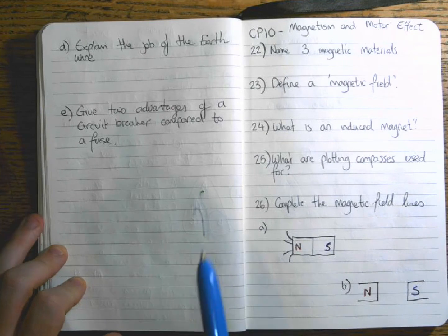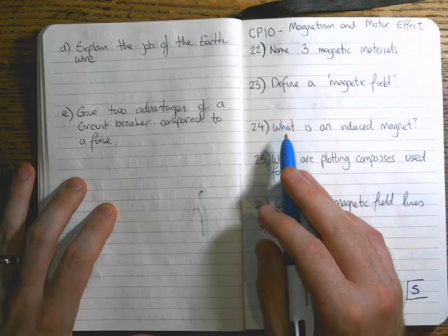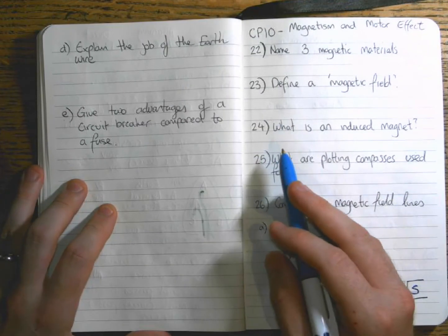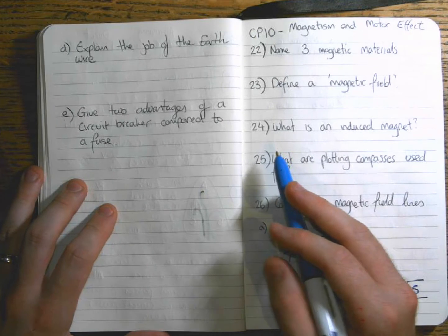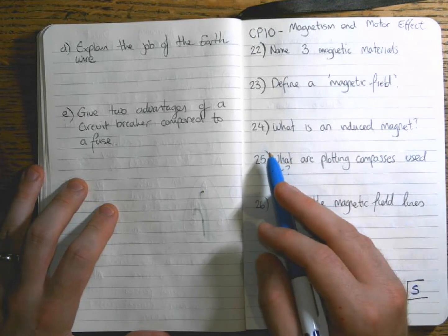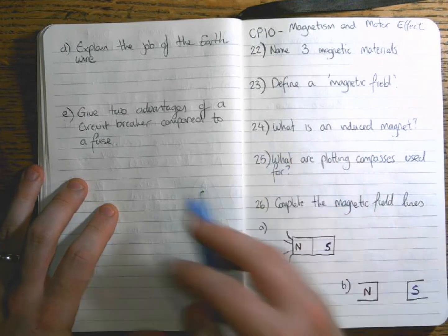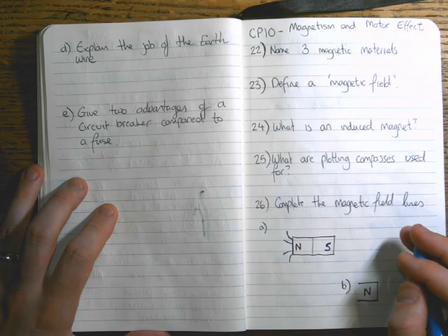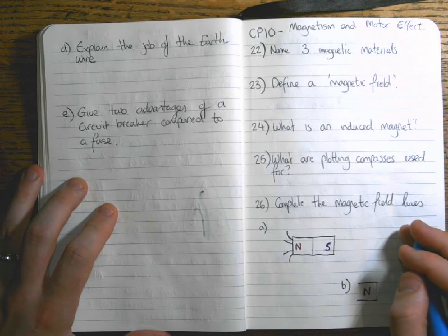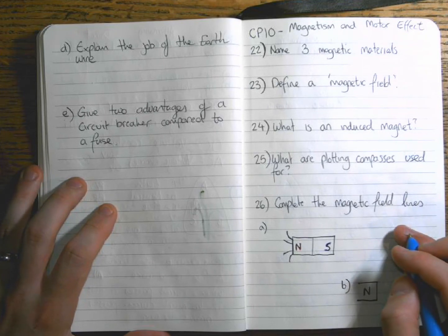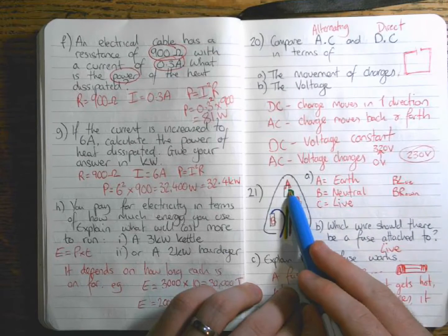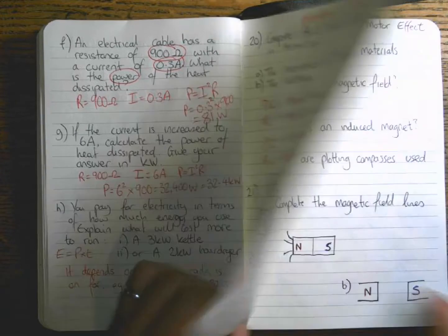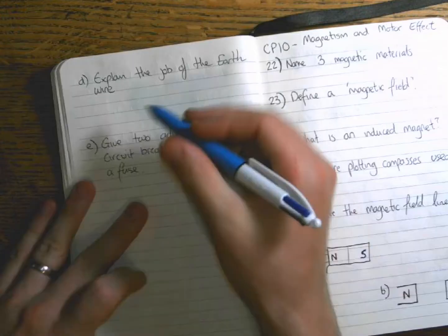Okay, the earth wire will always be connected to the metal parts of a device. So for example, on a hairdryer, usually the body's made out of plastic because plastic's an insulator. But inside the hairdryer there may be metal parts, and those metal parts will be connected to the earth part of the wire that goes to the hairdryer. And the reason for this is that